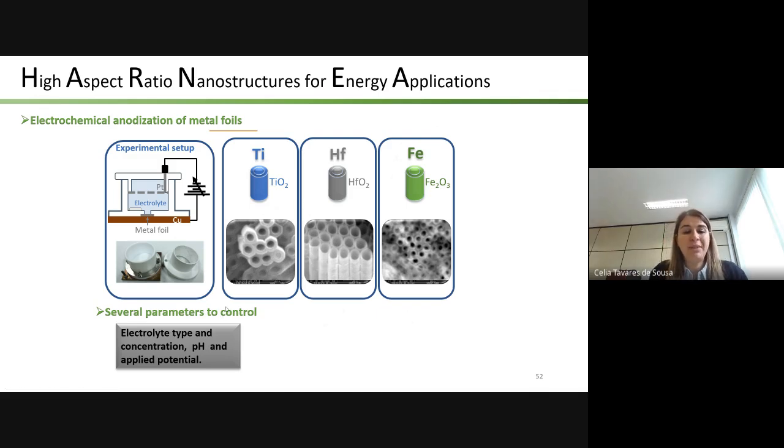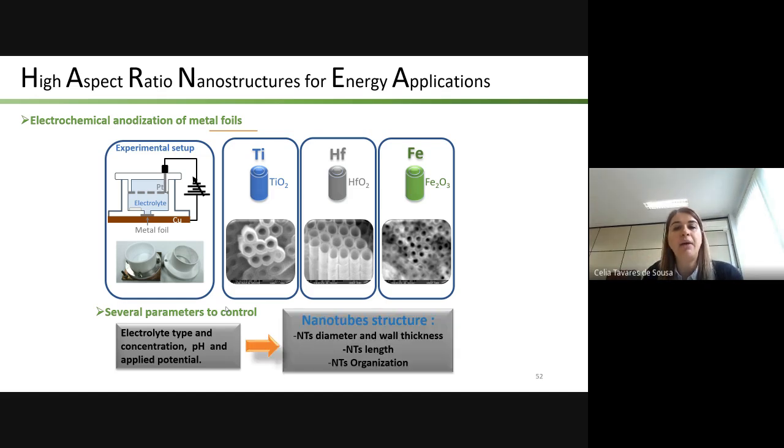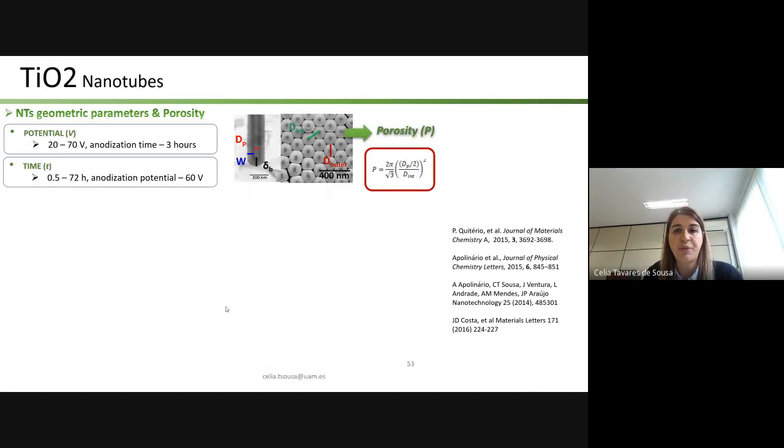We perform the same anodization method that we performed to produce alumina membranes, but using different electrolytes and different anodization potentials that can be optimized depending on the nanostructure that we want to obtain, depending on the material, the thickness of the pore walls, the diameter and the length of the desired structures.